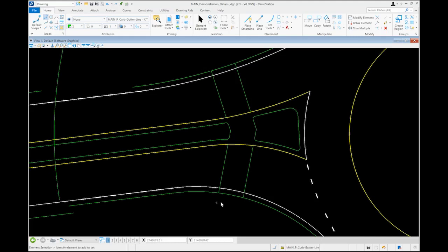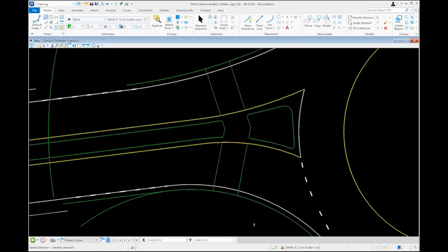So once we have those established, we now can look at our transition zone in between our 2 foot offset for our entrance curb and gutter and our shoulder on the approach and start to build in our bike amenities. The GDOT Roundabout Design Guide recommends an 8-to-1 taper to transition from the shoulder to the curb and gutter line through the entry. That 8-to-1 transition allows for a smooth merging of a cyclist that might be on the shoulder into the travel lane to traverse through the intersection as a vehicle.